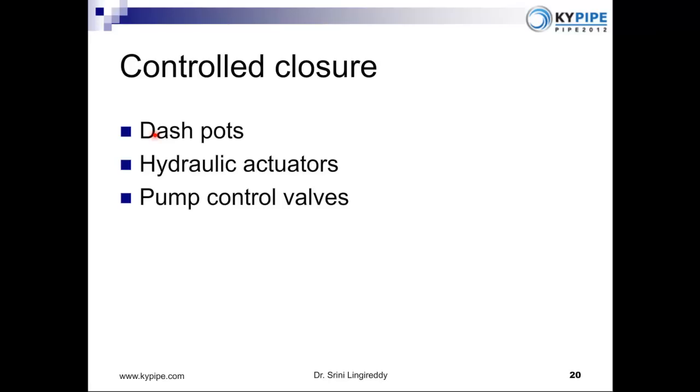The flow up to that point increases in the reverse direction, but then when the valve is only open 5%, and if there is enough resistance, the further slow closure of the valve is actually going to decrease the flow rate in a very controlled manner and minimize the hydraulic slam.